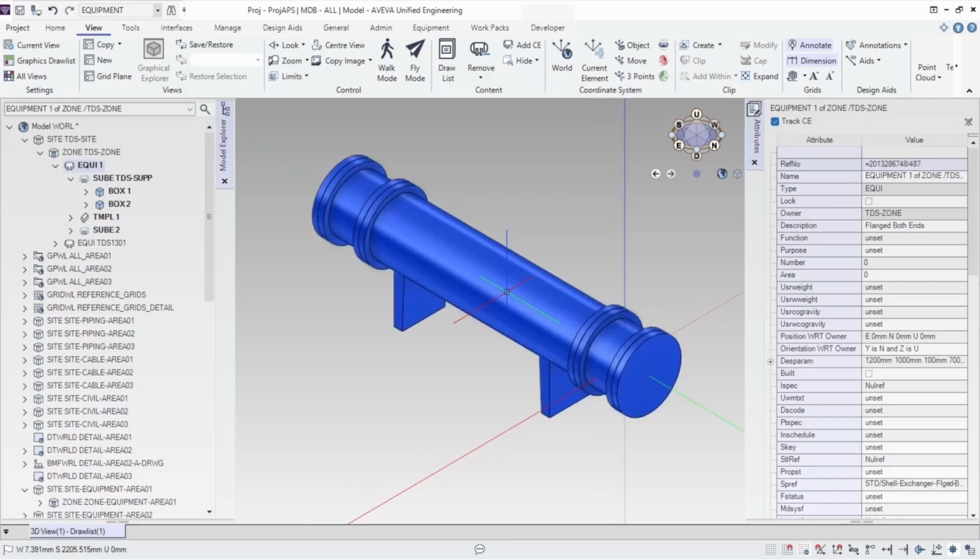We've now completed the process of creating and customizing equipment using templates in E3D. Starting from template selection, we defined parameters, created the heat exchanger, explored its internal structure, and made modifications such as toggling supports and shaping them with negative primitives. Through this exercise, you can see how templates make equipment modeling faster, more consistent, and much easier to modify, all without rebuilding geometry from scratch.